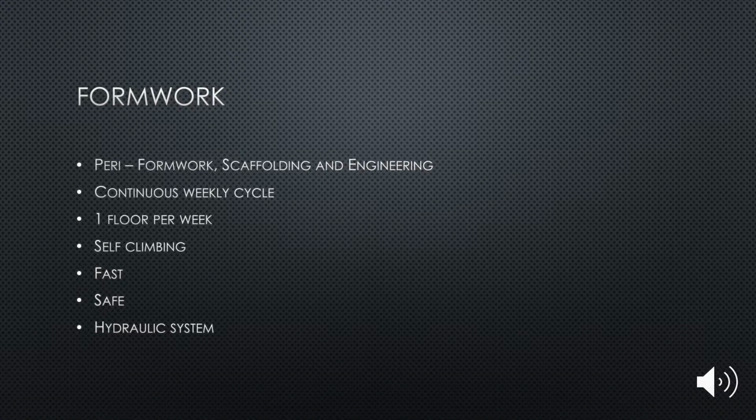They can simultaneously climb several units, which will ensure fewer leading edges and increase the workplace safety. The climbing units were connected to the building at all times, which ensured the climbing procedure was carried out quickly and safely, even in adverse weather conditions, particularly high winds, which you will get as the tower increases in height.